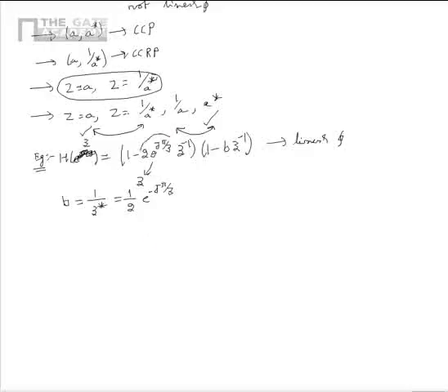So, from the property that zeros of a linear phase system form conjugate reciprocal pairs, we see that zeros are located at 2 e^(j pi by 3) and 1 by 2 e^(minus j pi by 3). Now, let us consider another case in which the system function of a linear phase LTI system is given as H(z), and the impulse response h(n) of the LTI system is real. It is given that a zero of H(z) is located at 3 e^(j pi by 4).